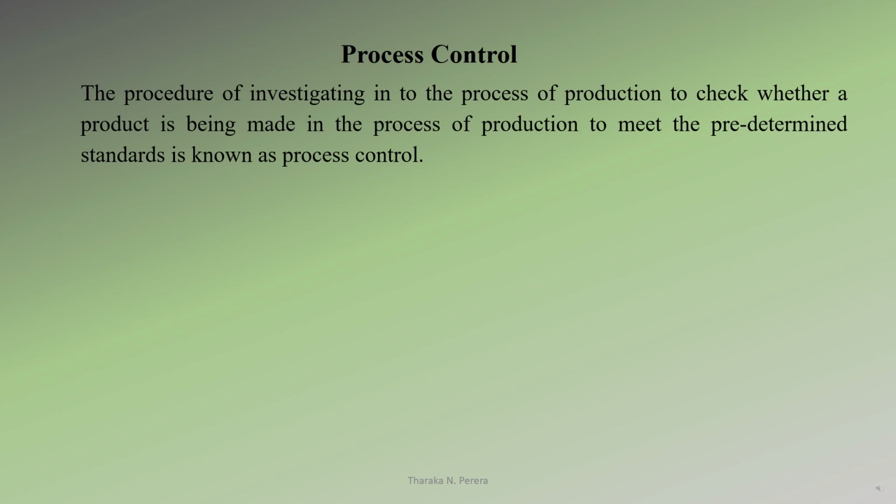We can use these techniques for process control. The first one is 100% inspection. It is the process of checking each product separately to find out whether there are any variations in the product. There are some essential situations to use 100% inspection in process control, such as for products which have high risk in usage, for products whose technology we want to confirm by 100%, and for products where the loss is unbearable relative to their cost of production.